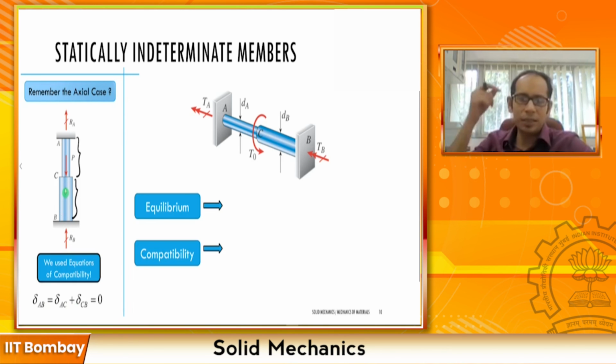And you had maintained the equilibrium and eventually derived the reactions. Similarly, for the case of the torque, we can also write the equilibrium equation for this one. Here you see the internal torque T naught. The directions are important. If you do your finger curling for the T naught, you will see that the double arrow for T naught points towards this direction, and these are your reaction torques that you have here.